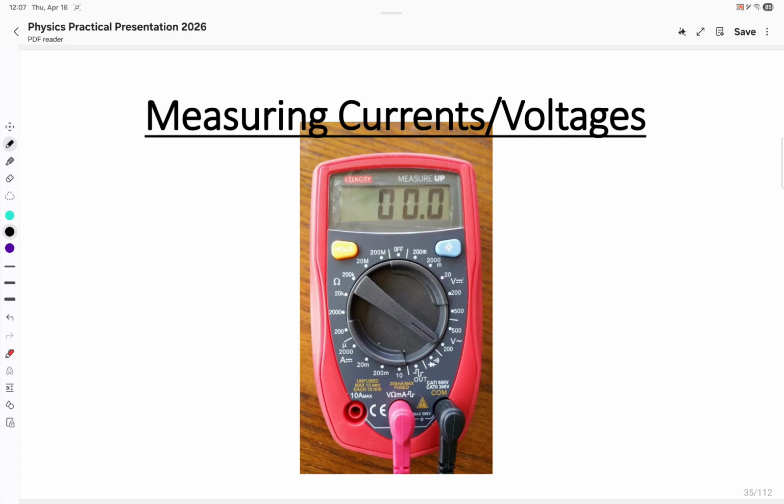A digital meter. You must remember one thing about a digital meter, that is where the knob, this dial mentioned here, is being set and how these leads are connected. Always remember the black lead represents the negative terminal, and the positive lead represents the positive terminal for the digital meter. The negative lead must be connected where it is labeled COM, and the positive red lead is labeled where it is mentioned volt, ohms, amps, all the three symbols together.